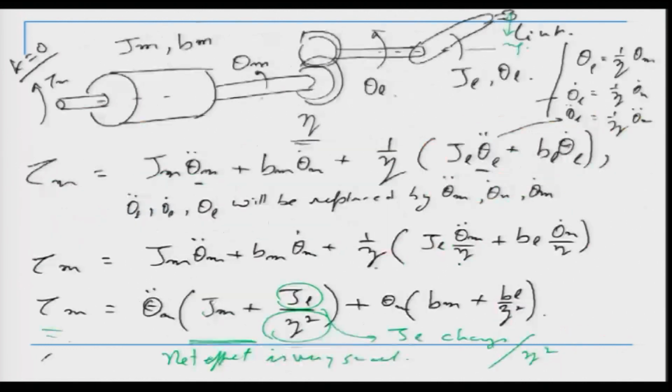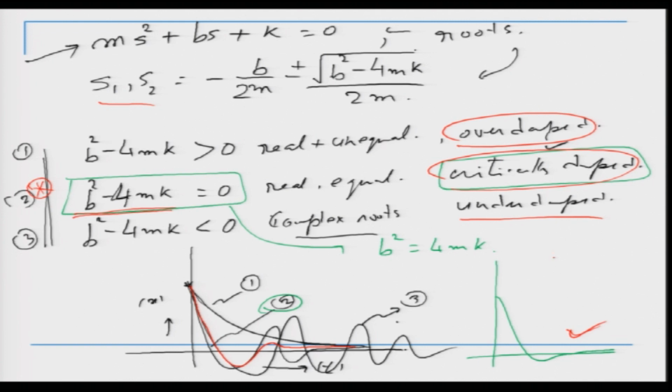So, doing this, we design a control system, choosing a value of Kp and critical damping. The first condition is Kp, you take some numerical value, then critical damping. Critical damping means B squared is equal to 4 mk. So, from here we can find the other values, Kp and Kd, and then design our position regulator or a tracking controller.